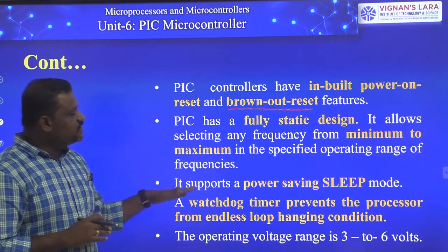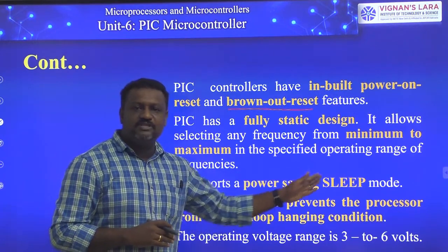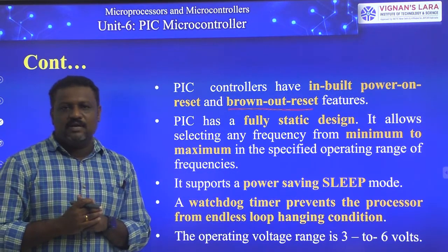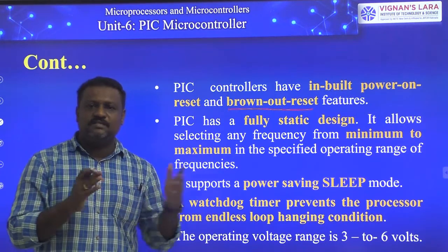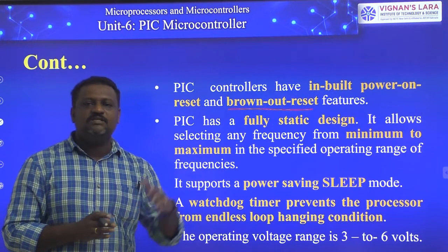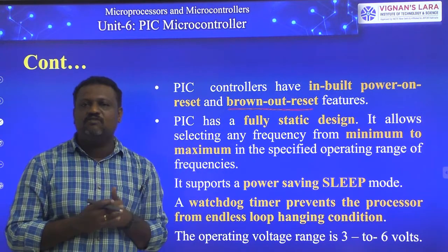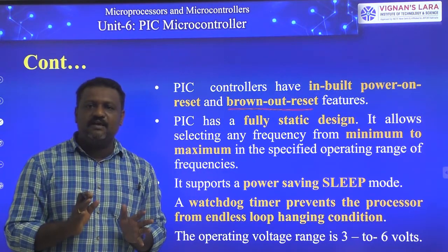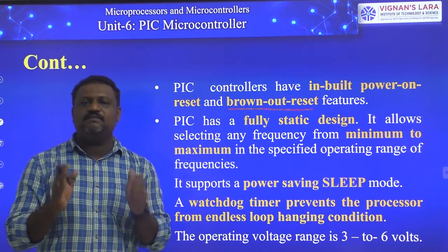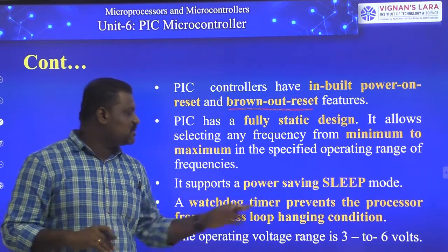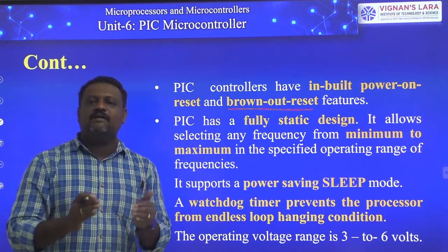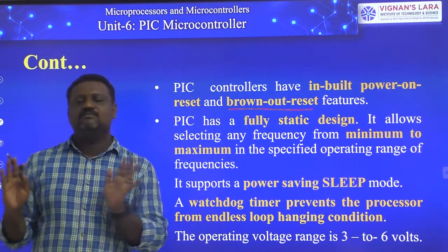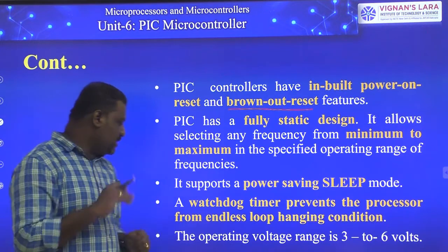And next, it supports a power saving mode which is called sleep mode. In the 8051 also, there are two power saving modes we already discussed: one is idle mode and the second is power down mode. In a similar way, in this PIC controller there is a power saving mode called sleep mode. In sleep mode, your controller consumes less power compared to the other cases. That you have to remember.